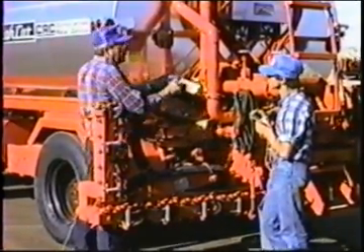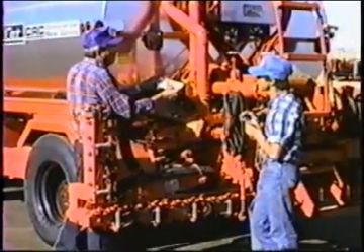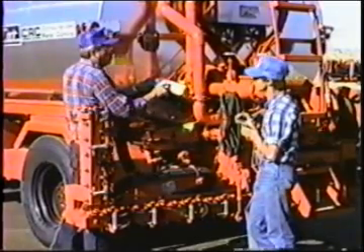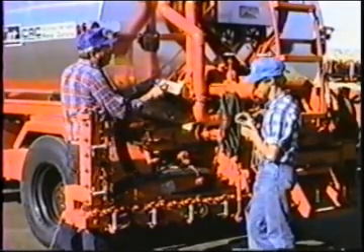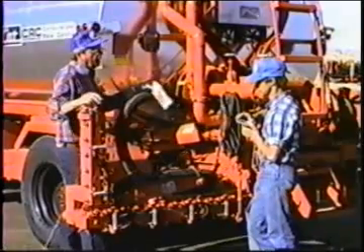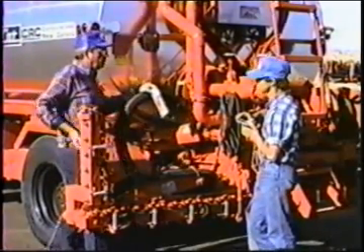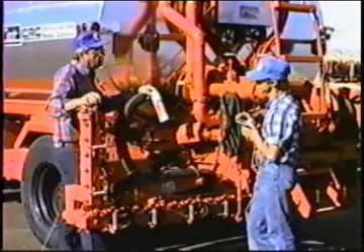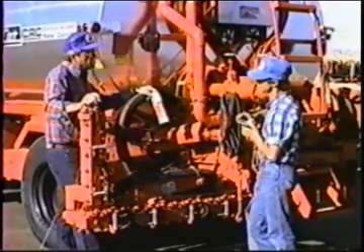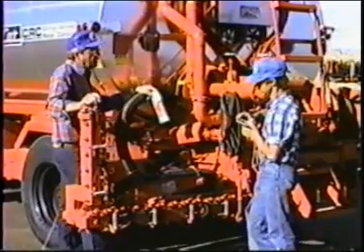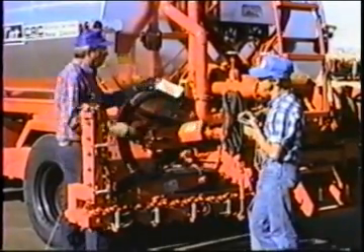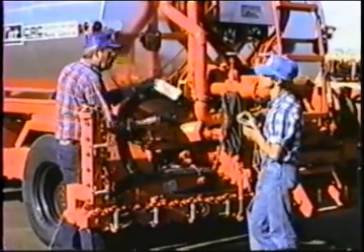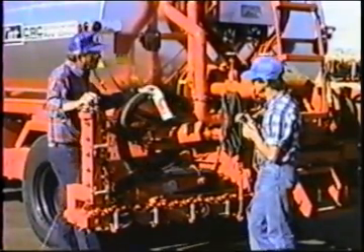And it's all in direct proportion. And it'll do just exactly what we did with the slide rule there. That is, once we've made the setup at some particular number, we picked 400 feet per minute to set up at. Once we've made that setup, as long as we stay in the same truck gear that we set up in, and as long as we stay at that spray bar width, our spread rate will remain exactly the same, even if we speed up or slow down, because the pump is speeding up with the truck and it's slowing down with the truck, and it stays exactly where it should be.